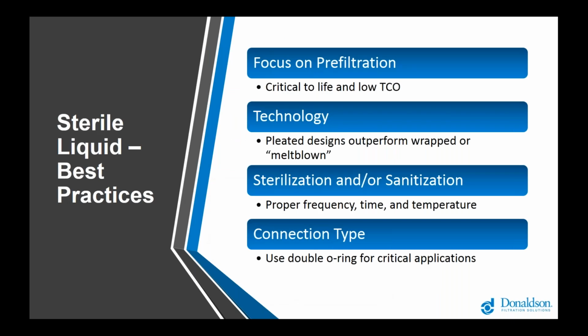So best practices in liquids require really focusing on pre-filters. Liquids are a lot more viscous than gases, and therefore they hang on to contamination much more than gases. So they're often, in effect, dirtier. So it's important to design systems with proper pre-filtration so that the more expensive final filters that are doing that sterilizing job can remain in operation for as long as possible.